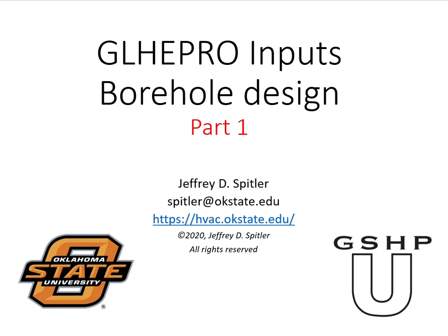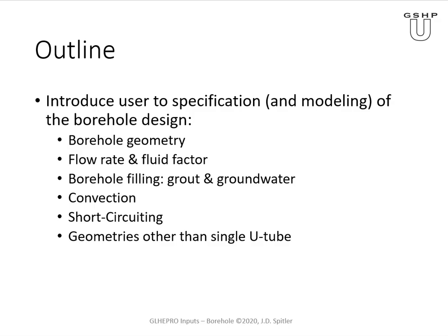In this lecture, we take up some more of the GLHEPRO inputs, in this case, the ones related to the borehole design, sometimes called borehole completion. So we're going to talk about specification in GLHEPRO and to some degree how the modeling of the borehole design works.